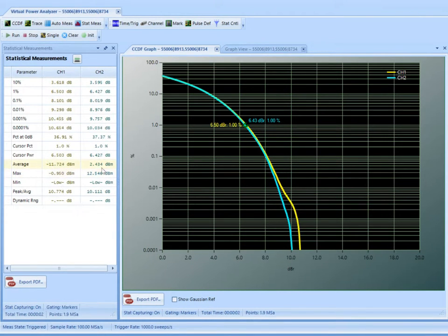look at our average power, and see we have our gain here, but we also are looking at peak power at various points in time. Yellow being the input to my amplifier, blue being the output of my amplifier, and then we have different cursors here. This is my average power percentage of time, and then this is my peak power in reference to my average. So as I start increasing the amplitude into the amplifier, I will start seeing a compression that is taking